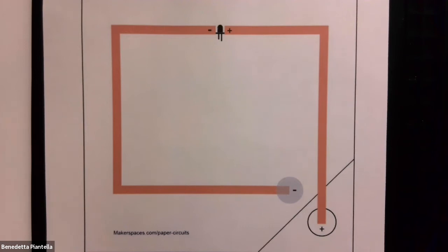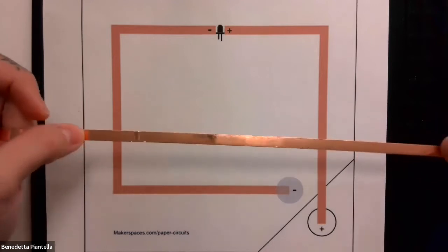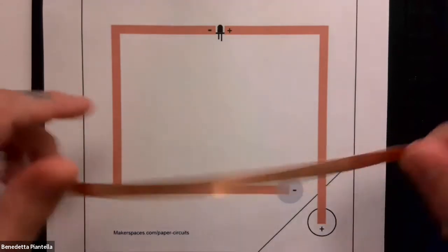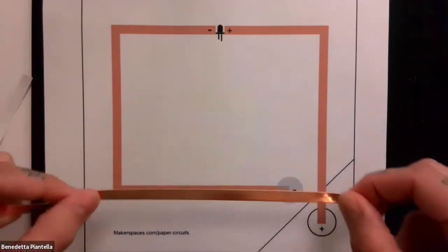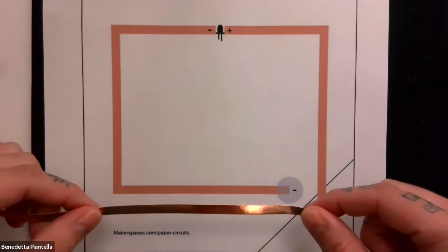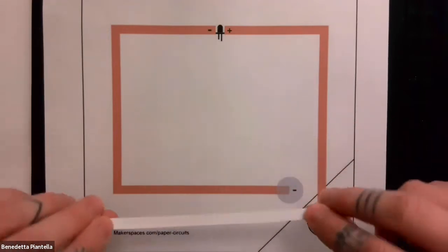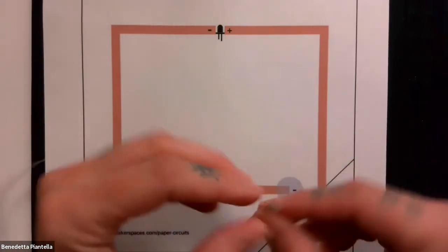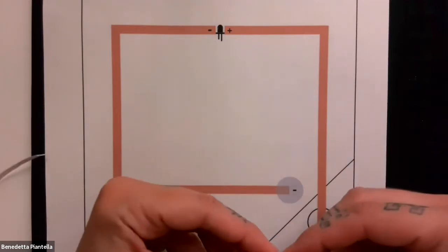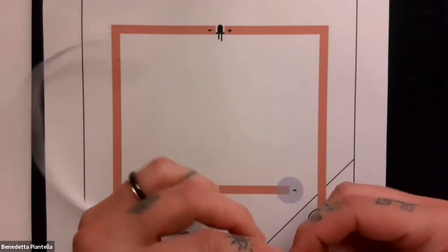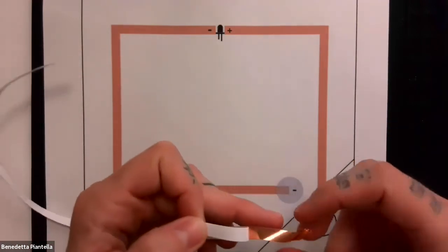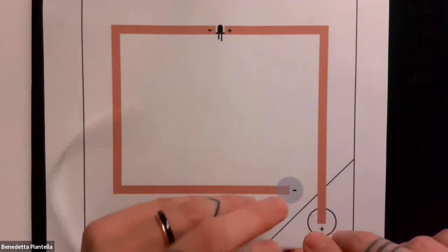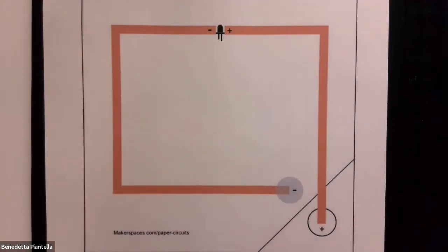I have a couple of tips from doing this for quite a while, and that came from experience and troubleshooting and frustration. Conductive tape is pretty conductive, meaning that it works really well, but the underside, although when you peel it, you'll see that the underside actually has copper at the bottom, is covered with the sticky layer, which sometimes makes it a lot less conductive. So there's a couple of tricks that you might want to keep in mind.